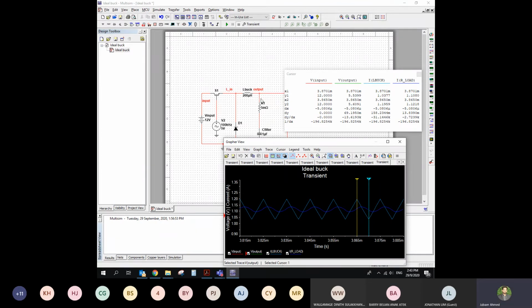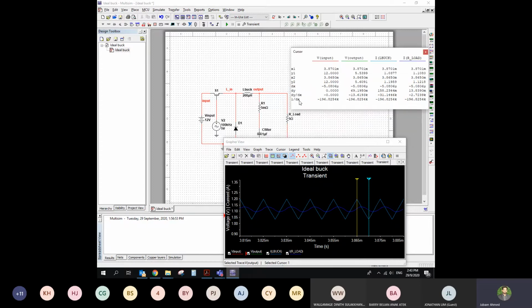So that's why, by adjusting the inductor value and the capacitor value, we have to make sure that our output is as close as possible to the theoretical value, following the duty cycle equation. Secondly, the output current should not have much ripple. The output ripple should be very low, because we are expecting a DC output here, since this is a DC-DC converter. So DC input, output should also be DC. But you can see, depending on the value of the capacitor, the output is turning slightly oscillating.